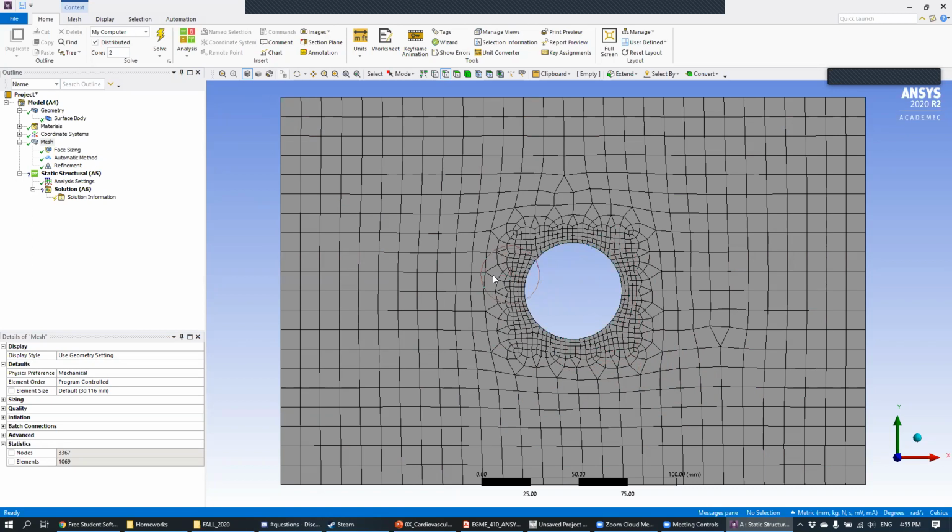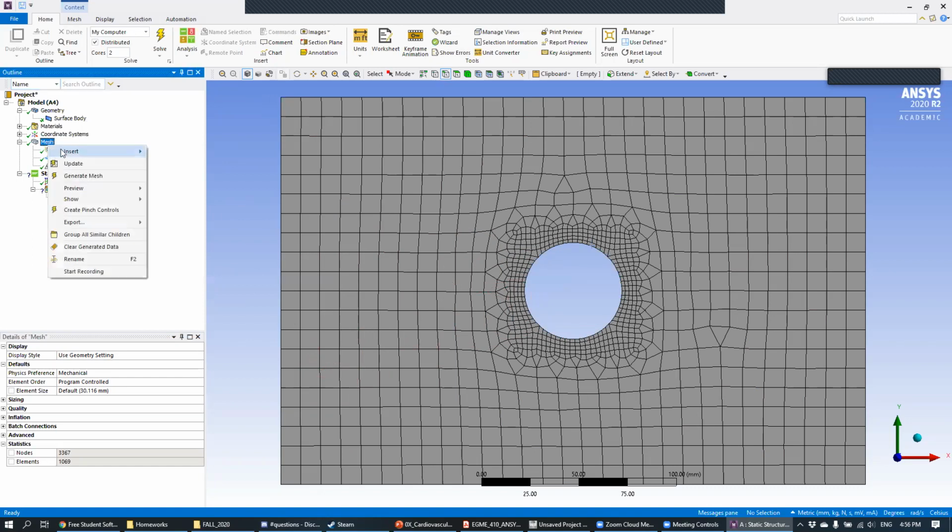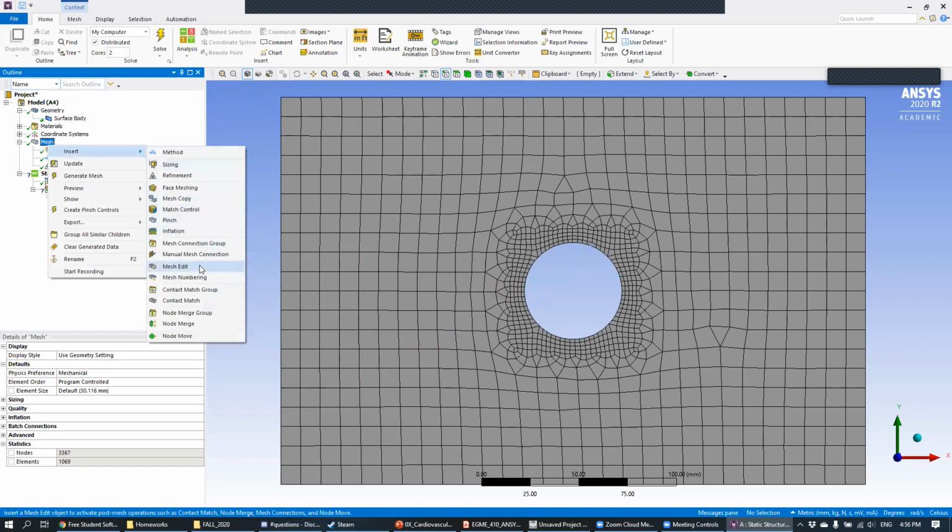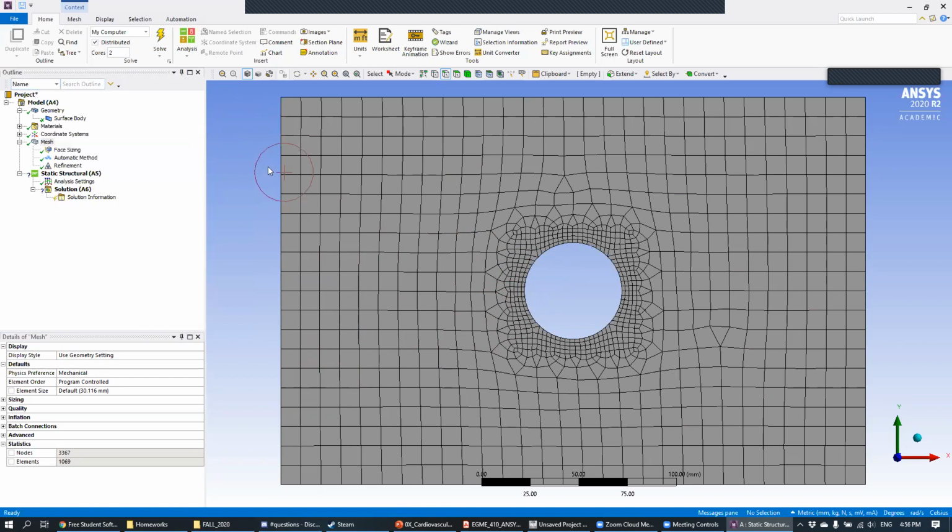And so that's the basics of meshing. Basically, for any Ansys job that you run, you want to make sure that you modify the size to make sure that it's appropriate. If it's showing up for your version, you can modify the methods, and you can change the shape and the element order. And anywhere in the mesh where you want to add some refinement, you can do so with that. There are a lot of other options for meshing, but these are the basics of what you need for every Ansys simulation.